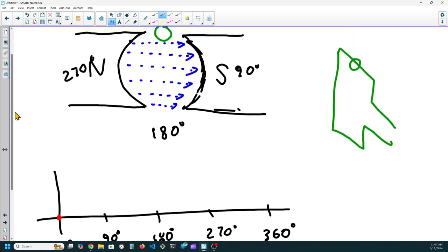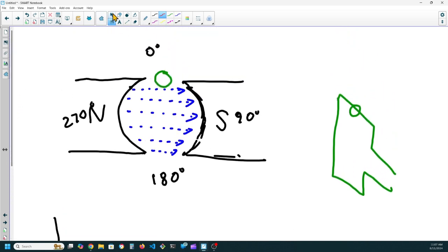But as we start to cut lines of flux, as we start to rotate and go through these lines of flux, here at 15 degrees, we're generating about 0.25 times peak. And at 30 degrees, we're generating about 0.5 times peak. And here at 45 degrees, we're generating 0.7071 times peak.